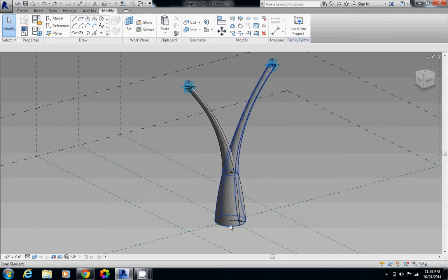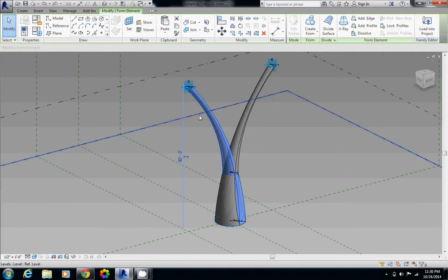So here you can see I started with the 4 circles and then used those to sweep and create a form. But rather than just connect each circle to the next in sequence, I selected all 3 in a row, and that way it makes one big curved form rather than a bunch of segmented linear ones. And so I think that's a more interesting approach when you connect it to this surface, because there are a lot more interesting ways that it can change and adapt.